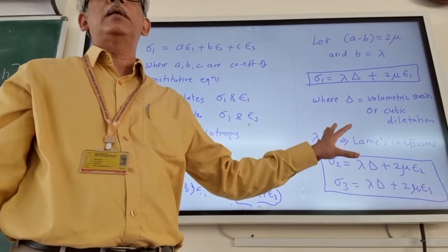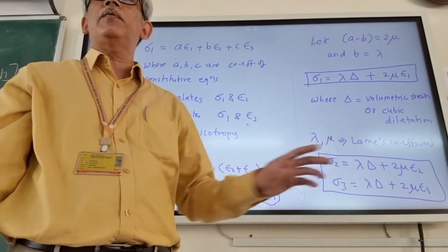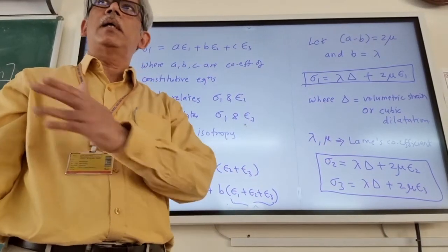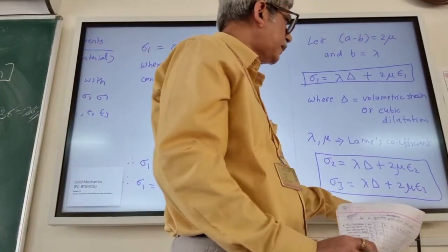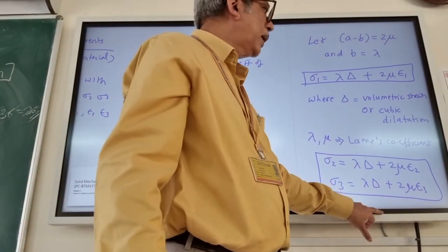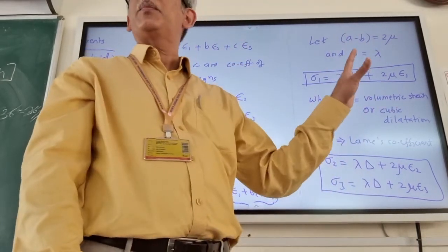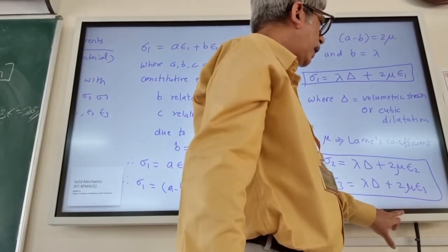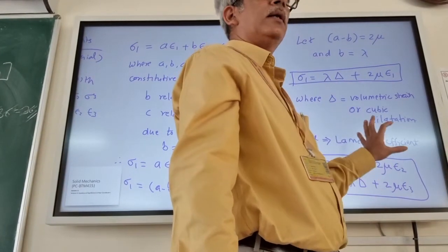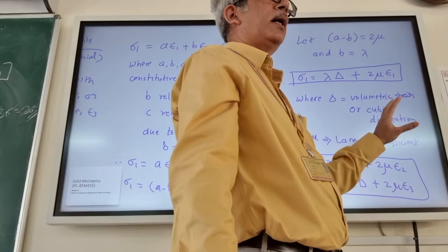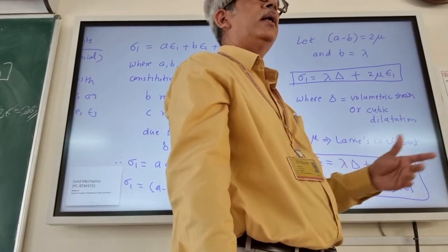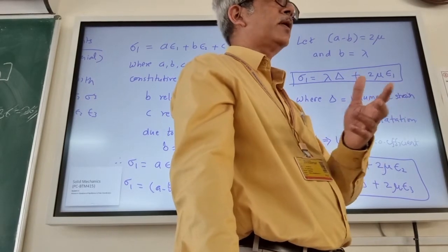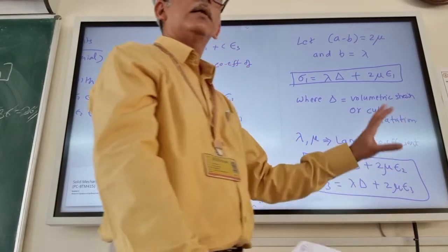We don't use the Lamè's coefficients; we go ahead with our regular modulus of elasticity and other related terms. But this is again for your information that such a thing exists. You should be aware of what Lamè's coefficients are, and they are nothing different than just another expression of the material behavior which is given in terms of the modulus of elasticity, the Poisson's ratio or the modulus of rigidity.